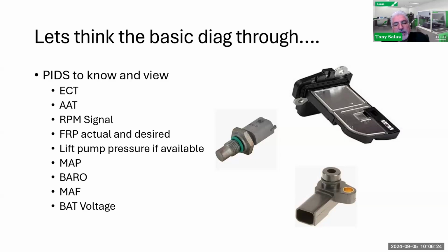Okay, definitely do that. So my suggestion to you, like I said, is get a known good truck. Let's say you work on a lot of 6.7 Power Strokes. Start recording some of those readings, take pictures, snapshots of a known good truck, so you can have that on hand, maybe with your phone, and be able to view them to see, hey, is this even close to what I'm working on? This will help me a lot. So definitely, it'll help.